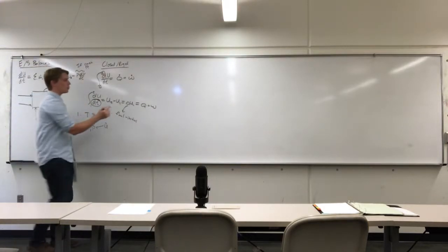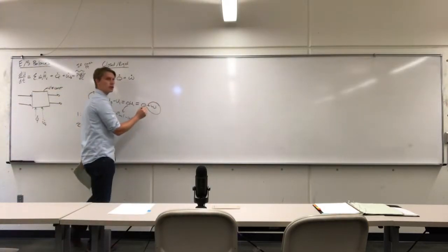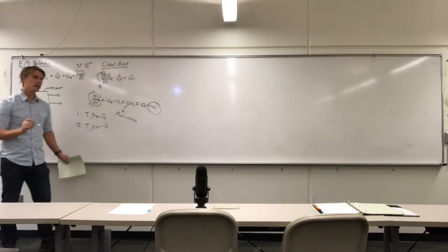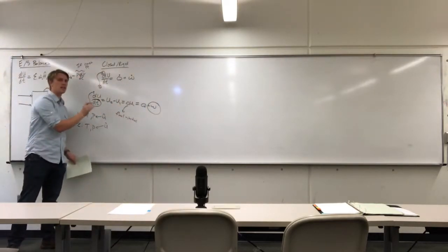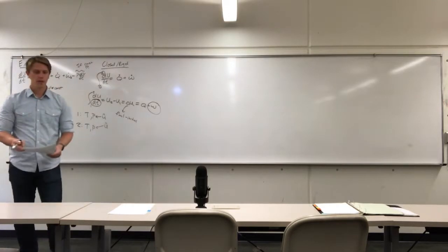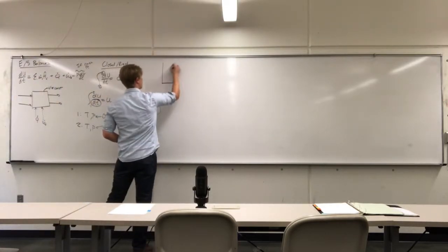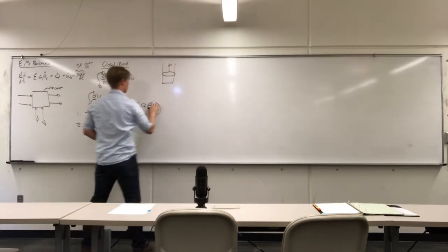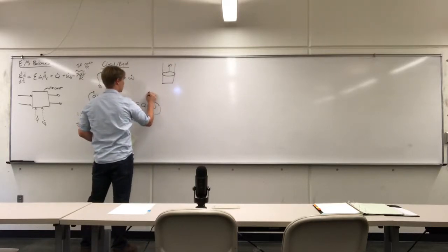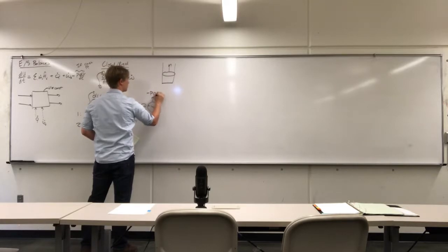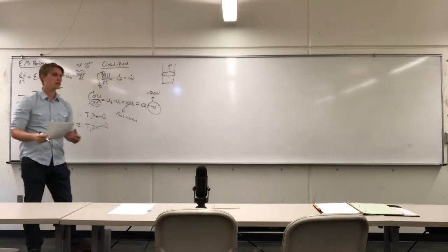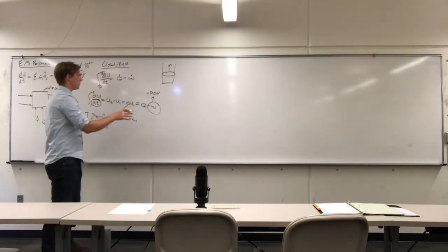Now, if you're extracting PV work here, then it really does matter the path and the time, right? Because work is not a state function. So if we are doing the classic piston cylinder device, in this case here, this isn't shaft work. Let's say this is PV work, so this is a minus P delta V, right? So that would be volume expansion work, which kind of transitions us a little bit into something else.